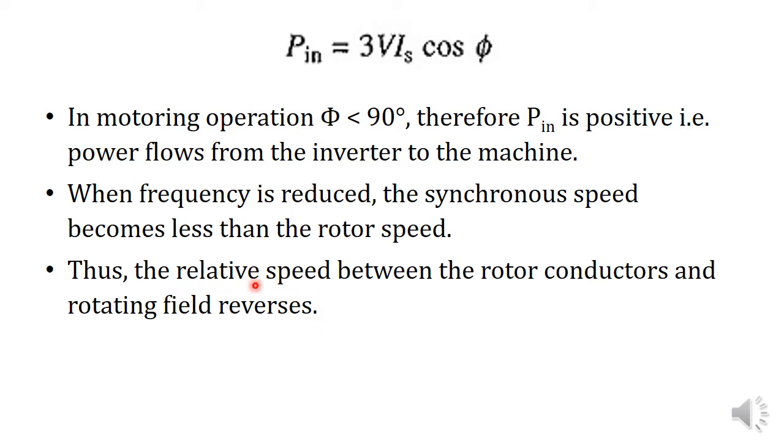During motoring, the relative speed was positive, that is omega s minus omega m. When the frequency is reduced, the relative speed, omega s minus omega m, becomes negative, since synchronous speed becomes less than rotor speed.